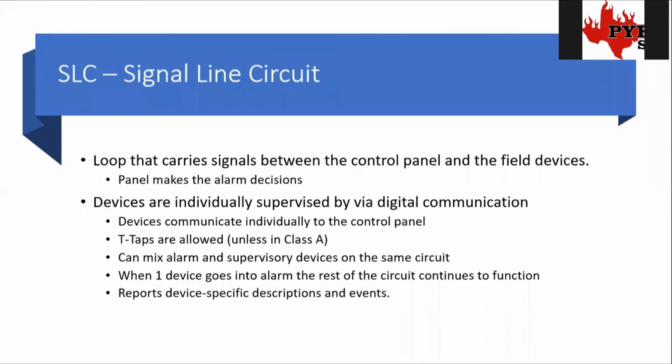And then what we've replaced it with is much more intelligent, much more efficient, but it's also much more expensive. And that's the SLC, the signal line circuit. This is a loop that constantly carries communication between the panel and each individual device. They're always talking back and forth.